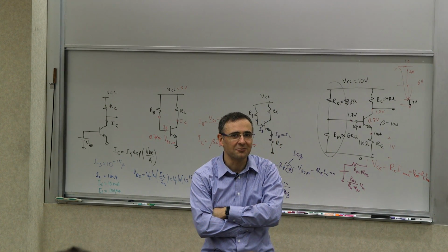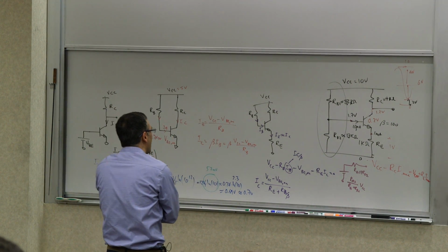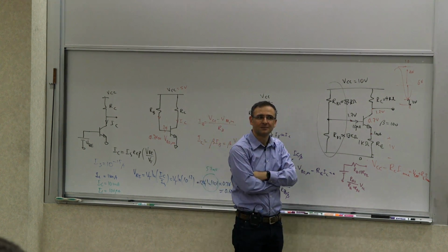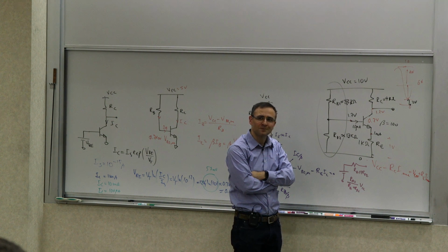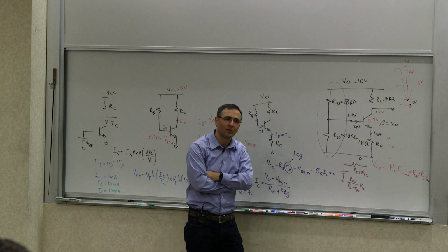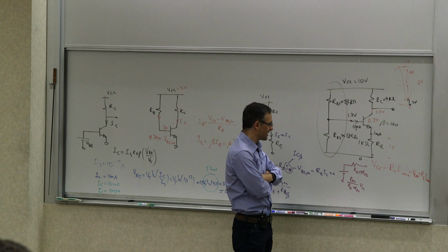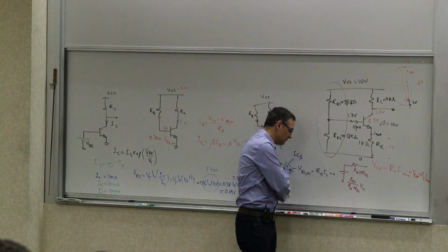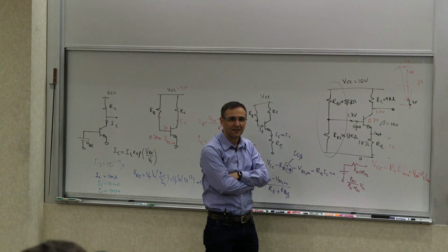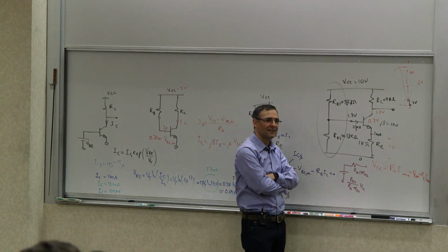Less than 4 or less, right? Because also you have the RM. Yeah, it's 4, because it's 4 kilo ohm divided by 1.025. So your gain is kind of almost fixed now. But is that true? Do you really need to be limited by this? What is making your gain small? What is the thing that has made the gain really small? The primary component that has resulted in this gain being small. What is it? Well, RC, yes, but it's really someone else. This guy, right?